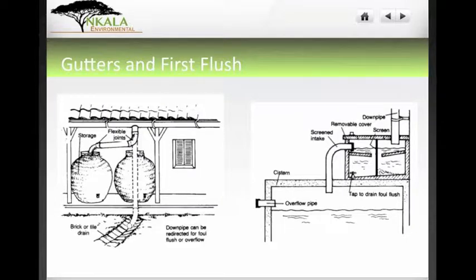Talked about the downpipe. You want to make sure you seal the joint where the downpipe and the gutter connect. That's very important because you don't want water leaking out through that. You want a clean connection. If you use metal, then you can seal it with caulk. If you use bamboo or something like that, you can use tar. So those are kind of material considerations there.